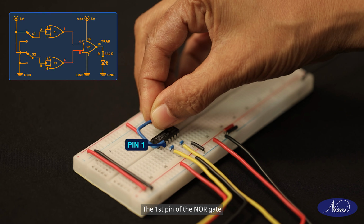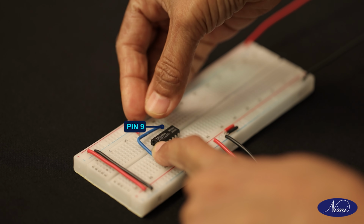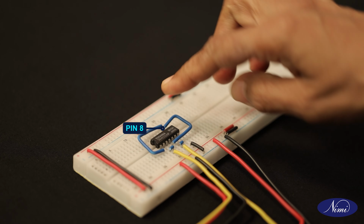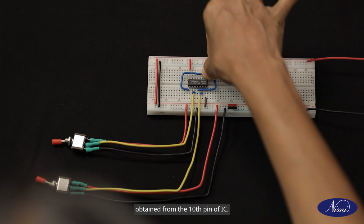The first pin of the NOR gate is connected to the 9th pin, and the 4th pin is connected to the 8th pin of the IC. The output is obtained from the 10th pin of IC.